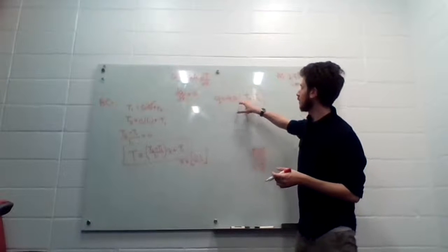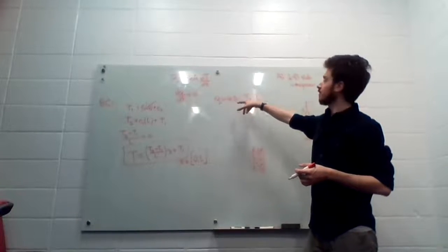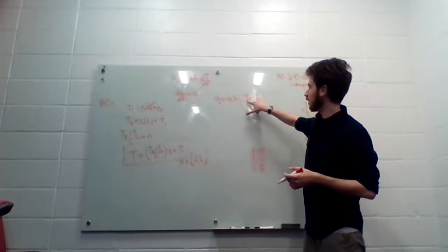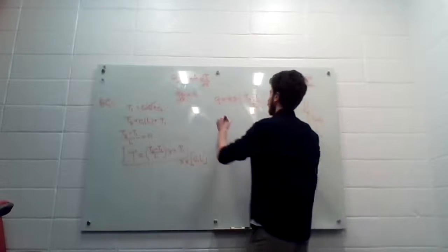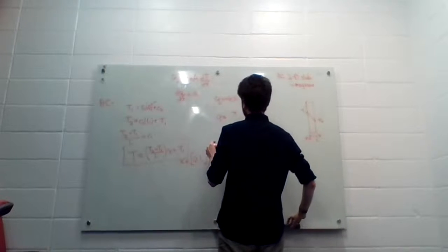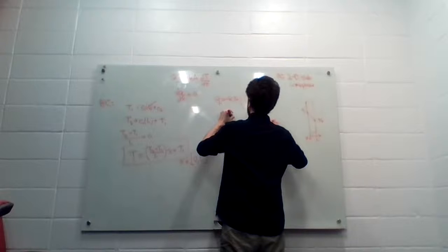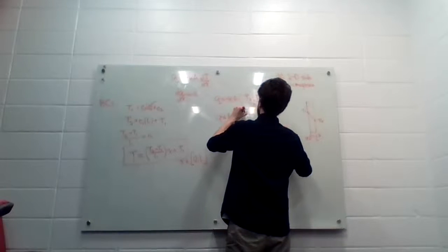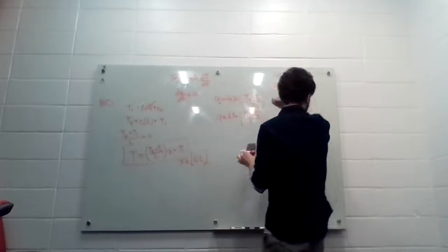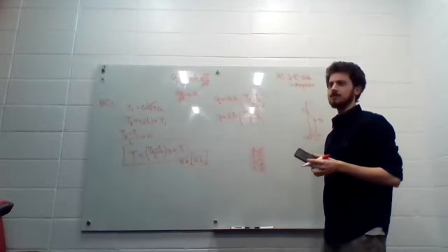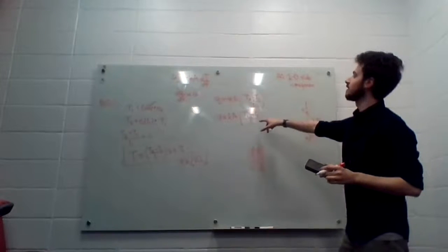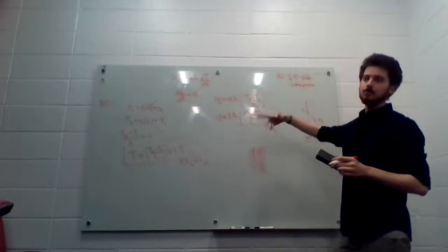So the first thing is we've got a negative here, we've got a binomial here. If I want to bring this negative in, so I don't have an extra negative out front, how does that affect the binomial? Flip something, exactly. So Q equals kA times (T1 minus T2). Remember the convention that we assumed is T1 is higher than T2. At least that's the intuition you should be working with. I think the math is the same no matter what, but think of this as now a positive number, right? T1 is higher than T2.